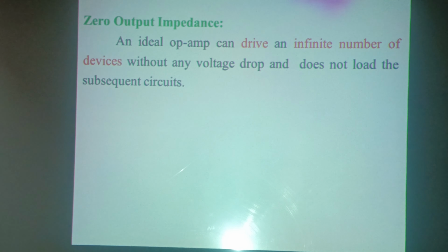The next parameter of ideal op-amp is, ideal op-amp has zero output impedance. Because of this, ideal op-amp is able to drive infinite number of devices without any voltage drop, and op-amp does not load the subsequent circuits.